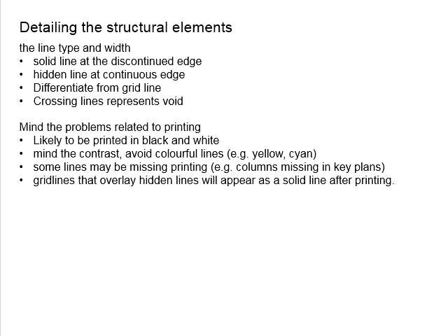Next, you need to be careful with the printing issues. This is another thing that most of our students did not consider. It will only be after printing, and normally after the students printed their drawing, very seldom do they look into the printed outcome. I recommend that once you've done the printing, please check carefully every single line, as if you don't do the proper setting in terms of the line type and line width, you will have problems with the printing, and this will affect the quality of the printing.